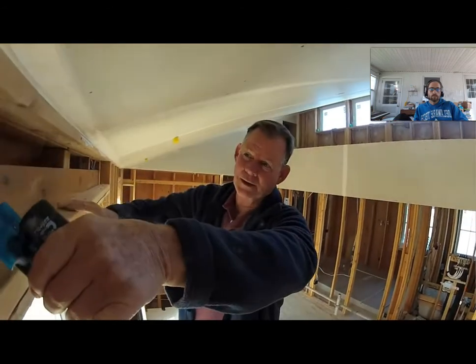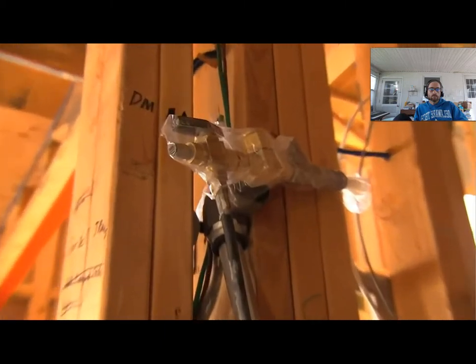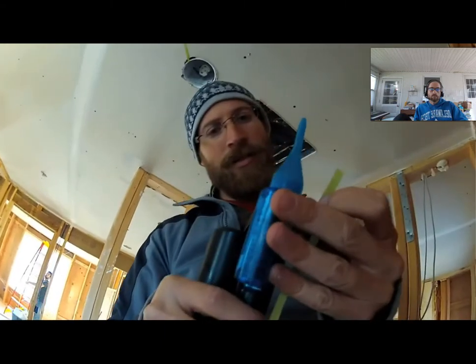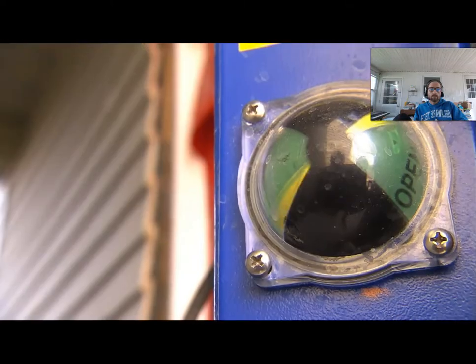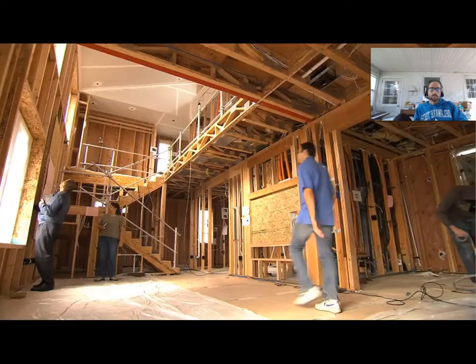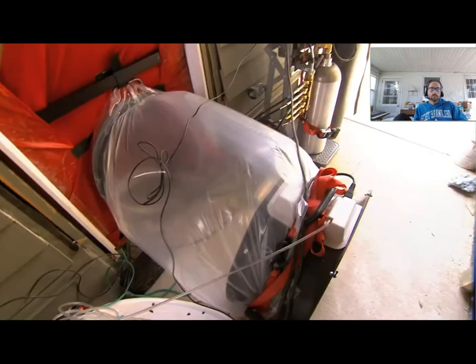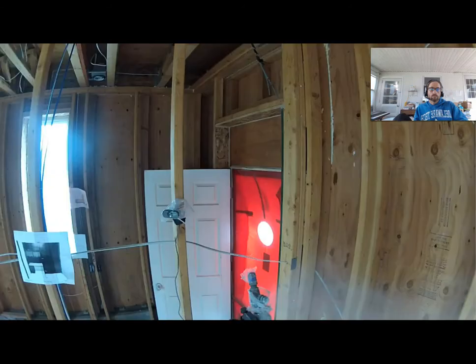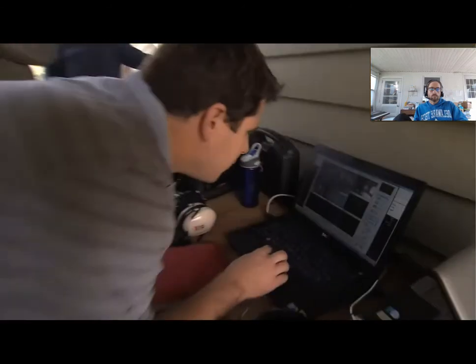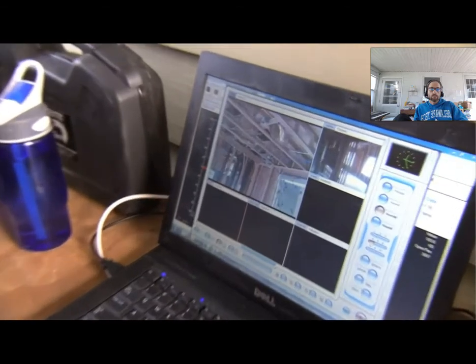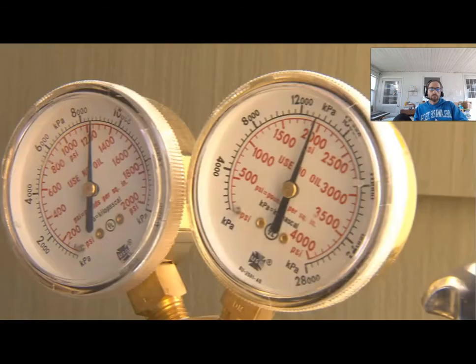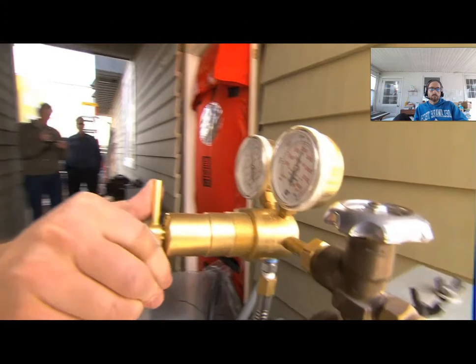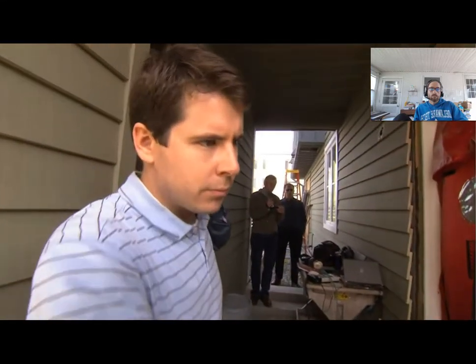So what we're doing today is sealing the Honda Smart Home here at Davis. And what we're using is a new technology that we're developing for sealing envelopes using an aerosol spray, and it is able to automatically seal buildings without a lot of the manual processes that go on in typical sealing. We're using a blower door to pressurize the building while we apply the spray. The aerosol fog on the inside is driven to the leaks by the airflow, because when you pressurize the building, the only place for the air to escape is through leaks in the shell.